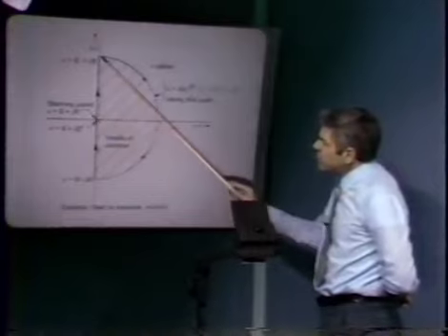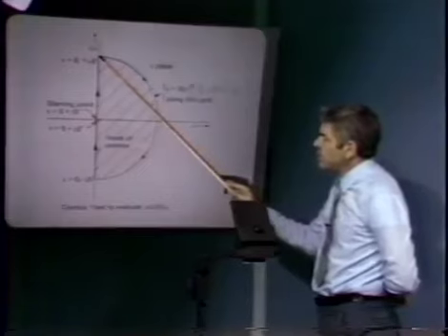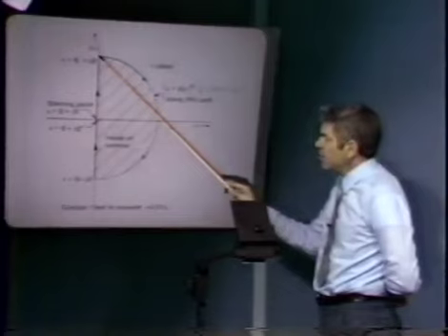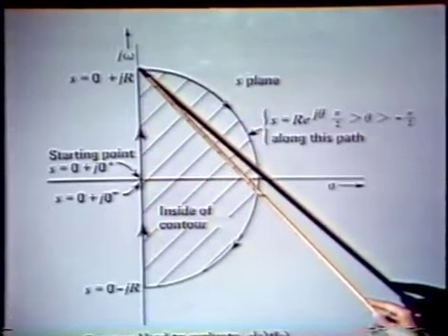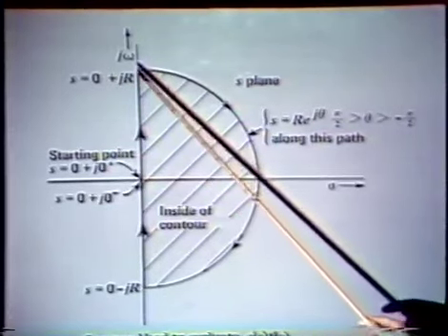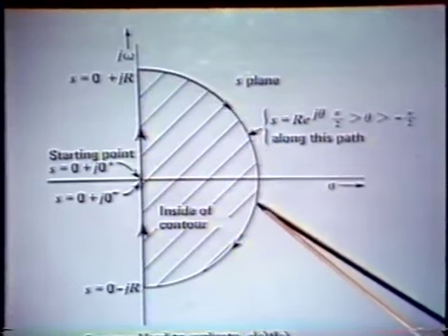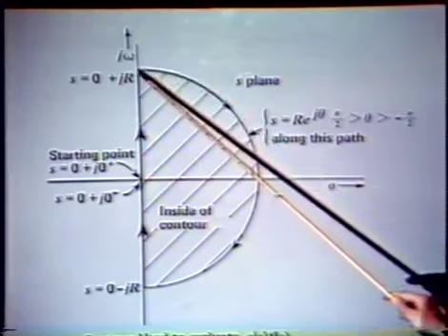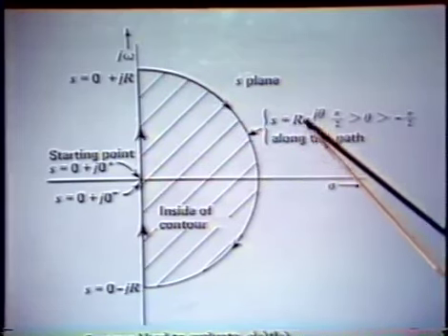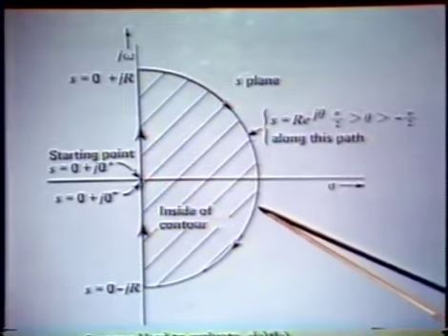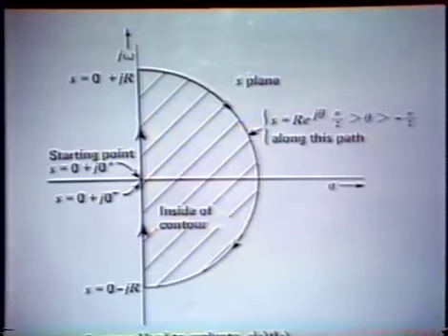We finally have reached a point in our construction where we have gone very, very far from the origin in the S-plane. In other words, out to s equals still 0 real part plus jr, where r is a large number. We then continue the contour into the region of interest along really almost any path, but conventionally a large semicircle is chosen, so we let s equal r e to the j theta, as theta goes from plus 90 degrees to minus 90 degrees.